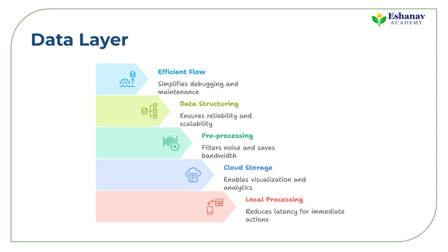The data layer is where raw sensor readings turn into actionable insights. This can happen locally on the ESP32 or remotely in the cloud. Local processing reduces latency, critical for instant responses, while cloud storage enables historical analysis, dashboards, and predictive models.